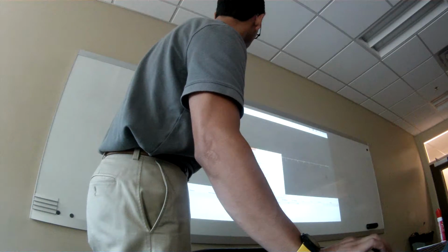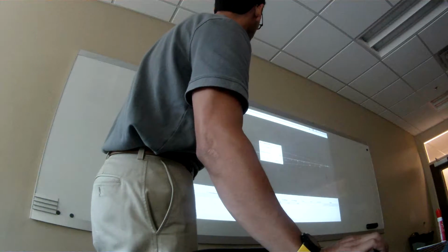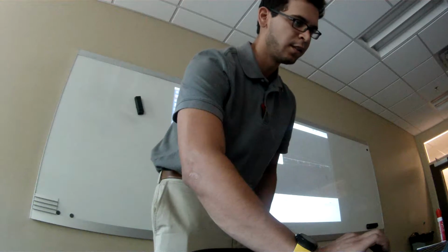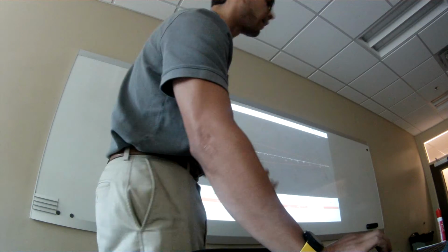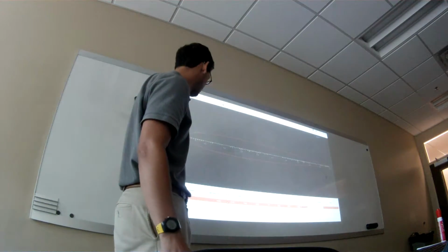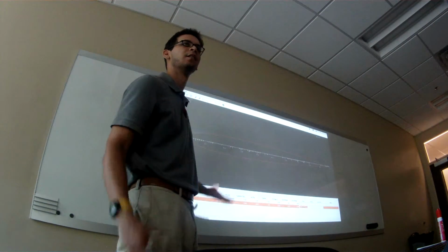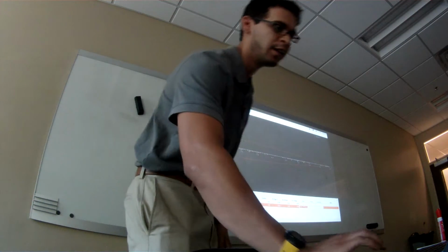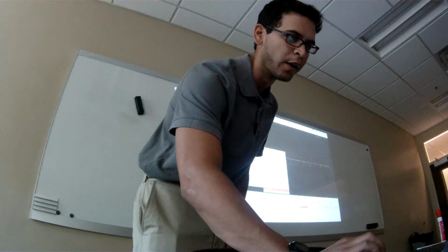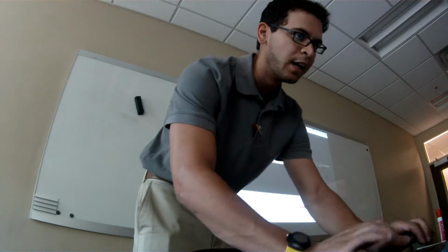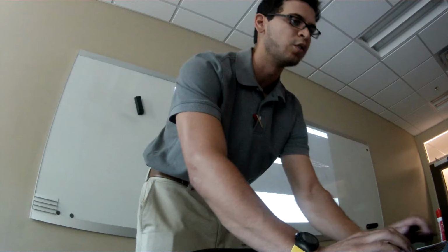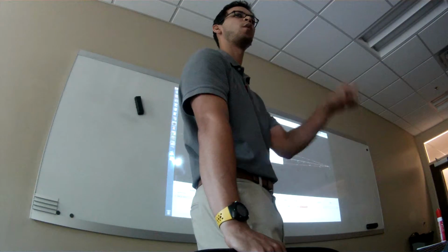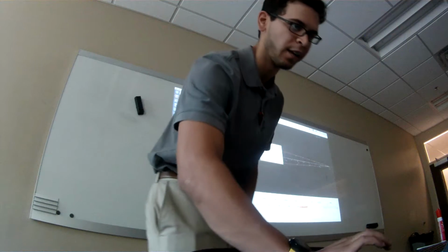I'm going to do foil, NACA foil, and you can do 4 or 5 digits. So I'm going to do a 0012 first. For some reason, I think I have a bug in my code. When I type in 0012, it changes it to a 0010. But whatever. If you notice, it's a symmetric airfoil. Maximum thickness is 10. If we add another foil, let's do something crazy like a 4212. So what's the first number again? That's 4% camber at 20% from the leading edge with 12% thickness.